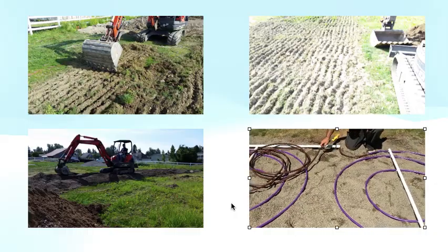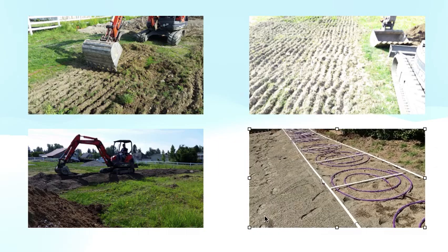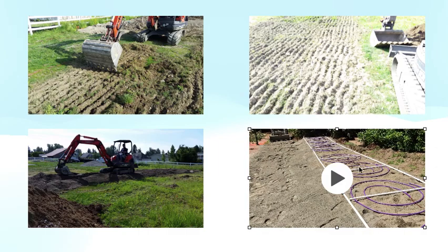But ultimately, what we're going to look at here, as we pan down, you can see you've got these 2 coils connected to each other, and so in this line of coils, every 2 coils have a connection to each other before you have a connection to your supply and flush line. I guess another thing to note here before we leave this slide: whether this side to the right is your supply line and this side is your flush, or vice versa, it makes no difference provided that you connect the coils correctly per the design.